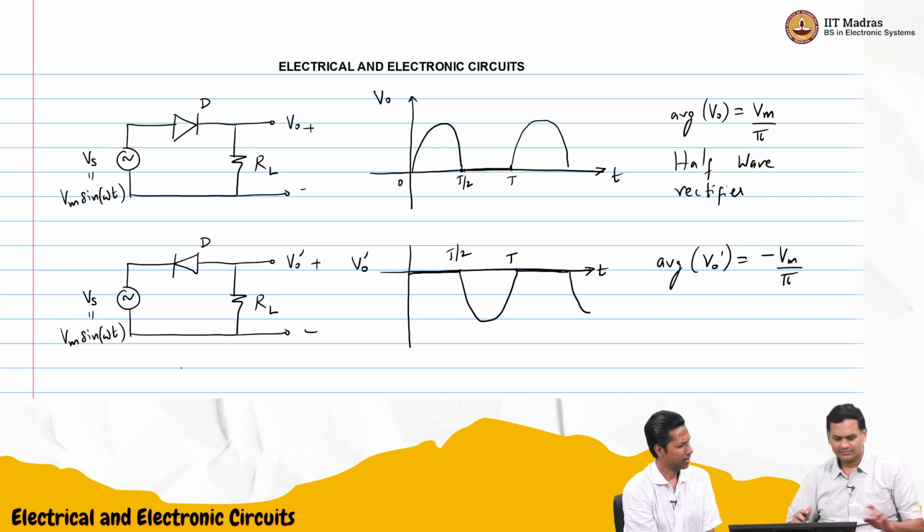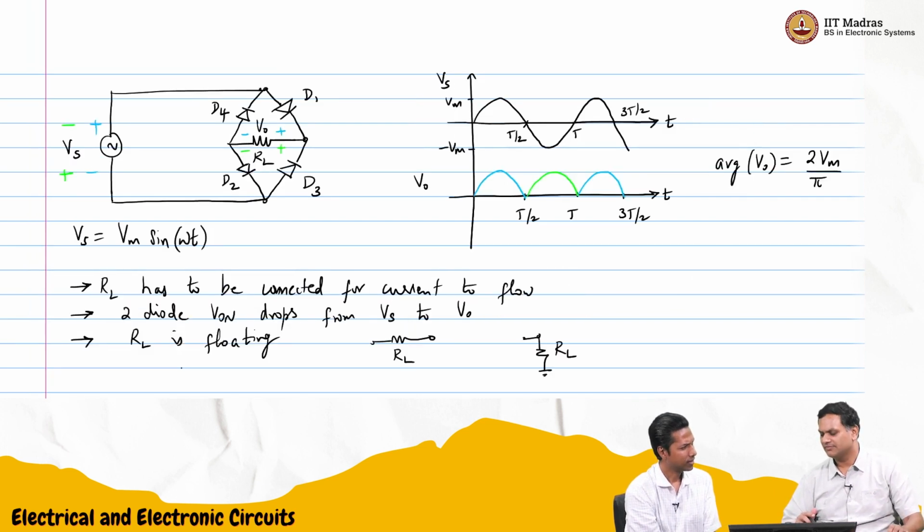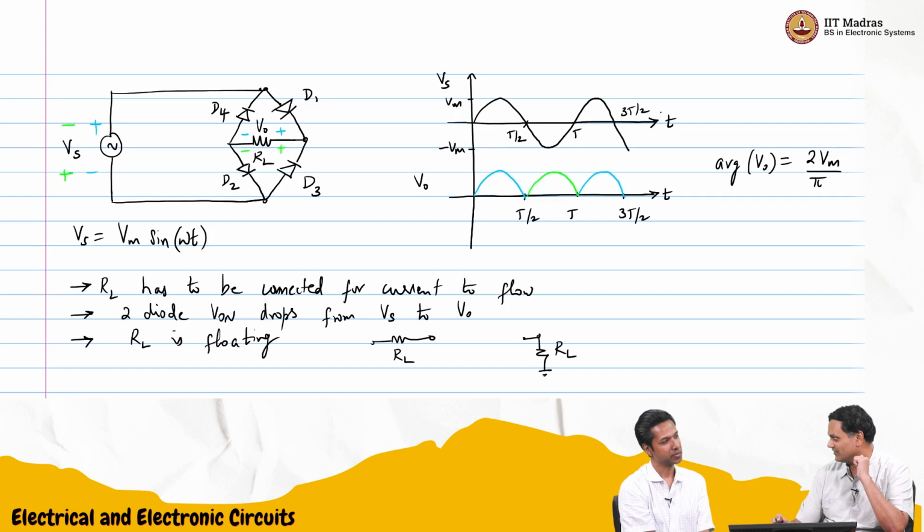Where do we use these rectifiers? One thing I noticed is that it became all positive, unidirectional. The only unidirectional circuits that we know are DC circuits, no? All the AC circuits we have seen so far have a full sine omega t. So even cell phone chargers may have some kind of rectification, because we connect them to 230 volt 50 hertz, which is a sine wave. But what is going to the cell phone is positive.